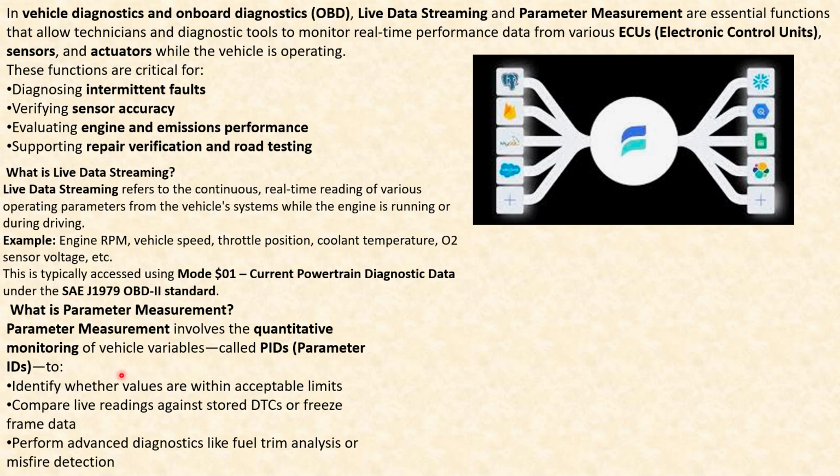And what is the purpose? This is meant to identify whether values are within acceptable limits, compare live readings against stored DTCs or freeze frame data, and perform advanced diagnostics like fuel trim analysis or misfire detection. So these three reasons are why this quantitative monitoring of the vehicle is so important.